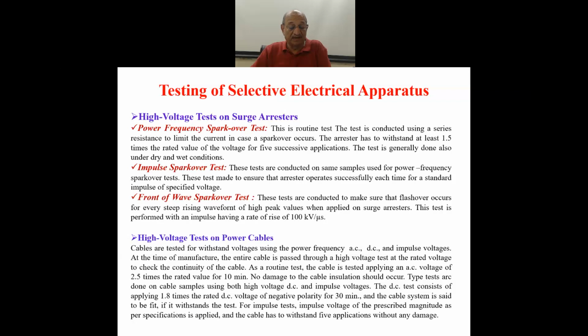Impulse spark over tests. These tests are conducted on some samples used for the power frequency spark over test. These tests are made to ensure that the arrester operates successfully each time for a standard impulse of a specified voltage.